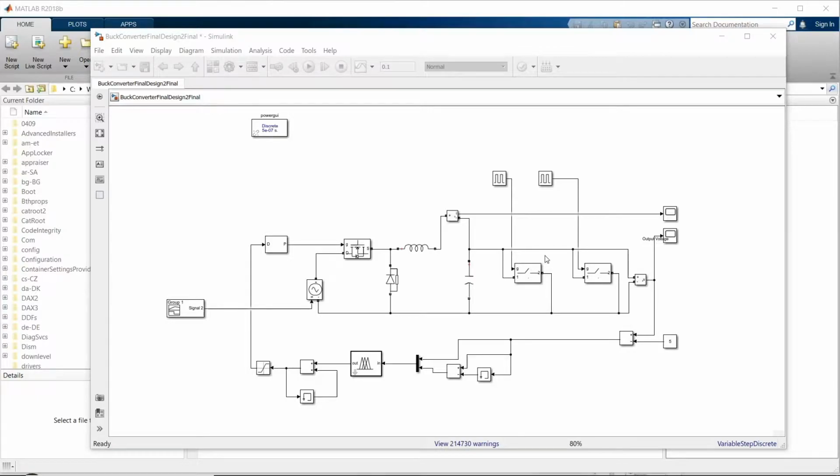And to check the robustness of my controller, I had introduced a load disturbance in my circuit. Then instead of using resistor, I use an ideal switch, which has a value of 10 ohm, and the second ideal switch also has 10 ohm. The first switch will on at 0 second, so we'll make the load in the circuit become 10 ohm at start, and then at 0.03 seconds the second switch will on, thus changing the load from 10 ohm to 5 ohm,